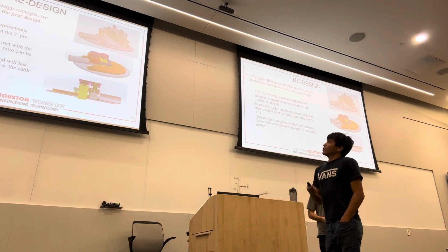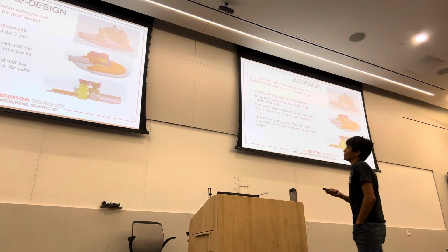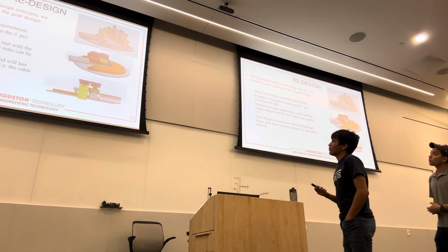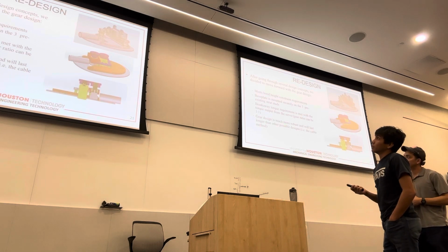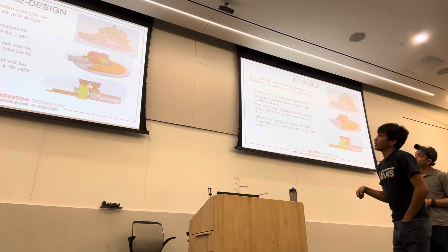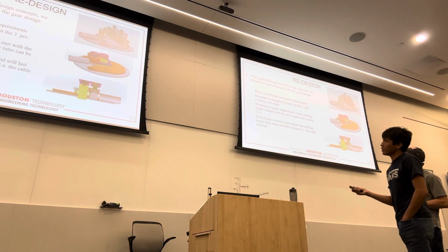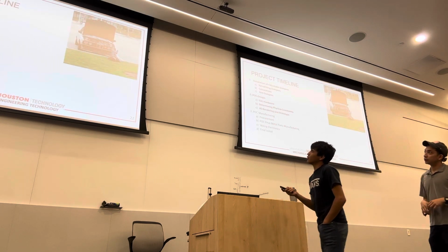So due to that, we had to do a redesign, and we went to a gear design, and we wanted to keep it consistent for the front and the rear. The redesign was a pretty crucial moment for us, but it just seemed like the stronger, more robust option. As you can see, it meets the hood requirements. The base plate is securely mounted, and then we can change the breakaway torque for the gears, and there's just some tunability with this design.